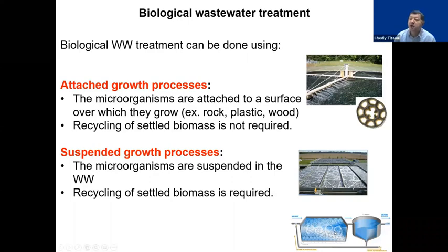You need oxygen, and also that air will mix the content of the reactor and therefore will suspend those microorganisms to occupy the total volume of that reactor rather than settle at the bottom of the reactor. So that's quite important. And you can see the air here on the top of an activated sludge process.